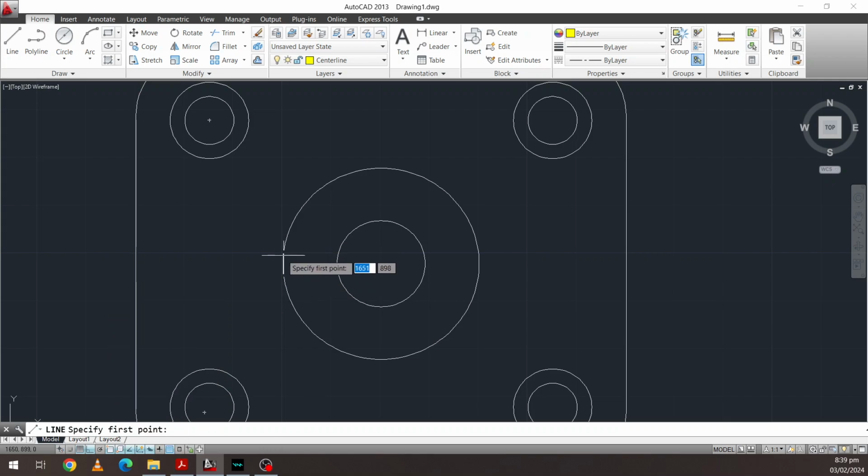It will show me the quadrant of this circle or any other circle that I choose. So what object snap tracking does is that it tracks your movements. So you can track or use any one of these object snap points as a reference. If I place my mouse there for just 1 second, it shows me the relevant object snap. But if I drag my mouse outside without clicking it, this green dotted line forms, which is simply a reference line or a tracking line in this case.